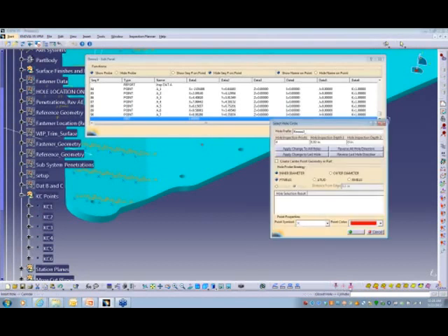So we have 2D hole, we have 5-axis hole, and point and vector hole. Then inside the strategy, so we'll call these holes, inside the strategy, we're going to probe the hole 4 times. We're going to go down into the hole 30 thousandths. We don't need to probe at a second depth. And then we have these strategies.